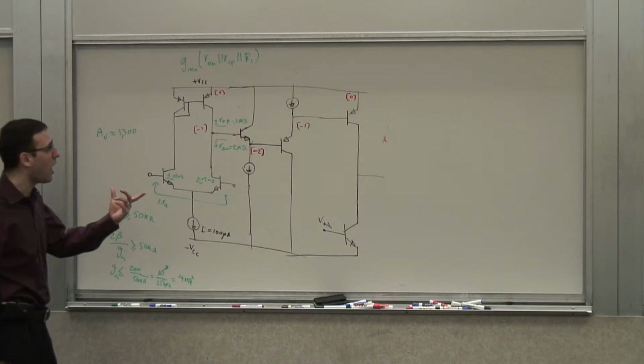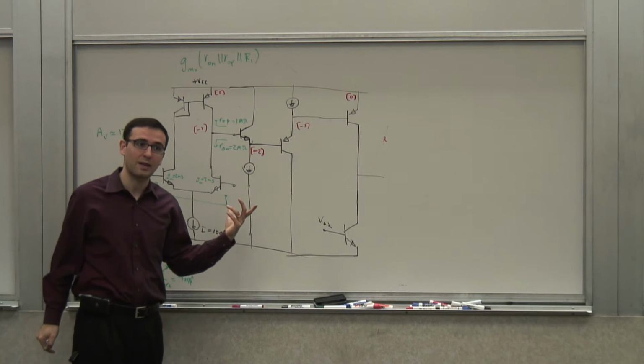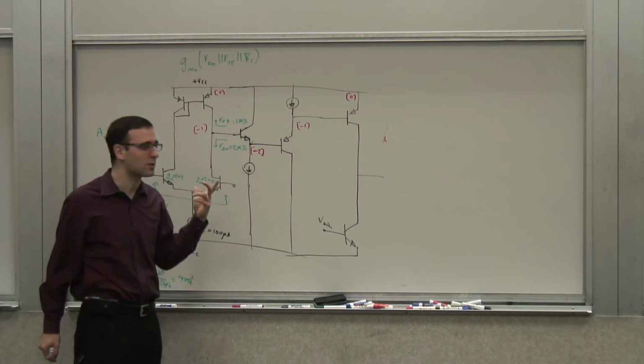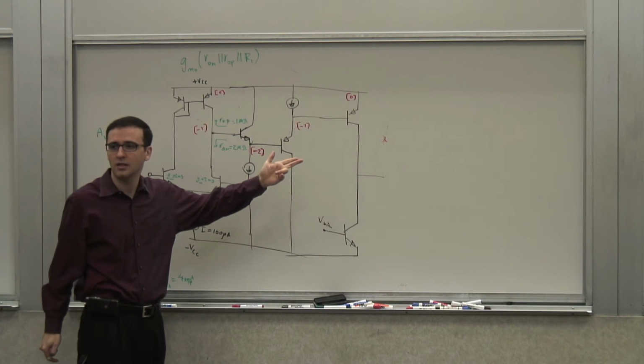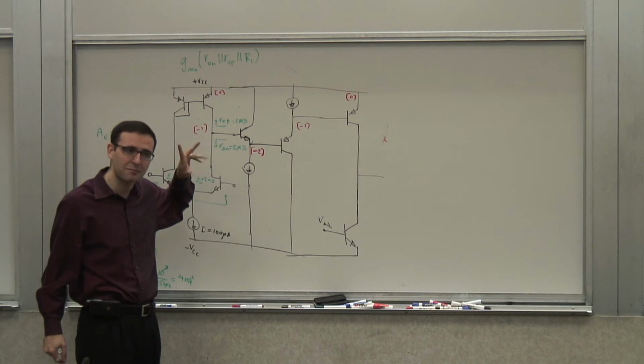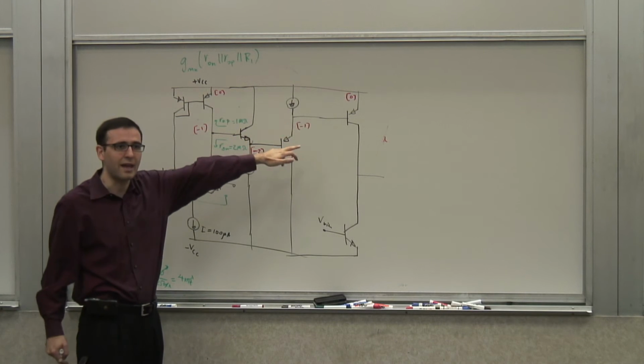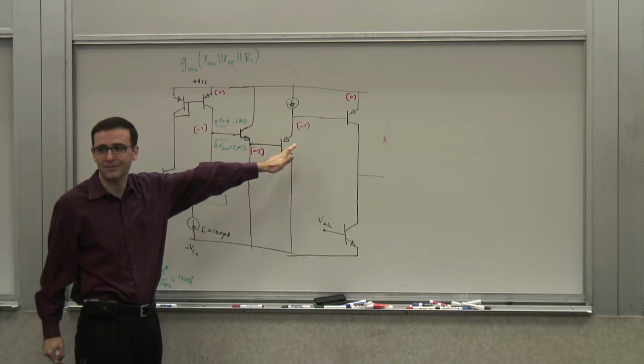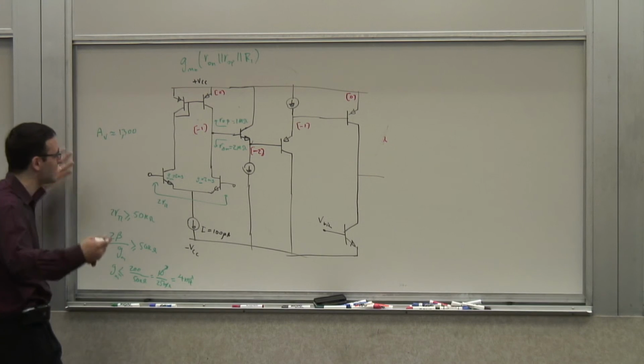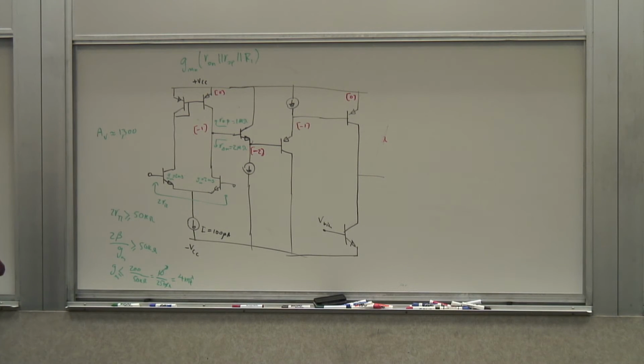Now, these are not a problem as far as that constraint. I want to get my gain in as few stages as possible, because these are not gain stages, right? We briefly talked about this gain bandwidth product. We said you only limit your bandwidth when you have high gain, but these guys have a sub-unity gain, so they're not going to be affected too much. But now let's calculate the AC gain for this stage, for what we have right now.